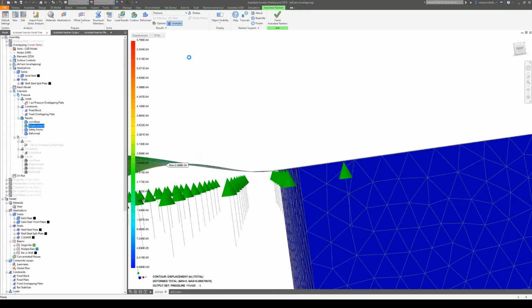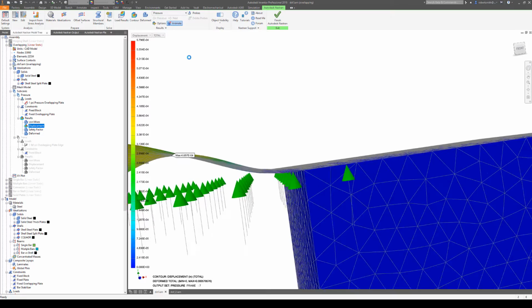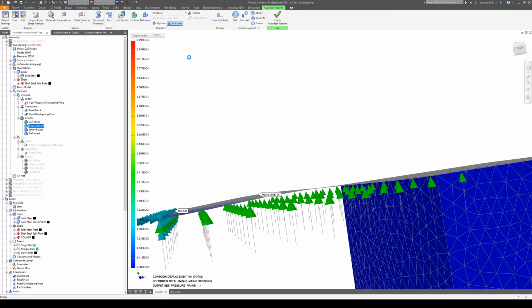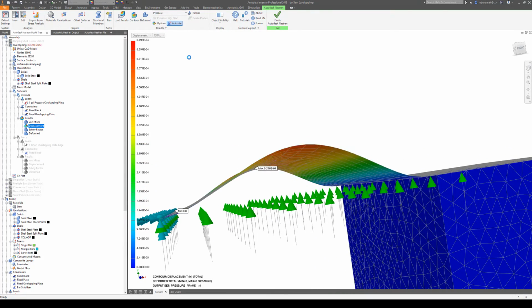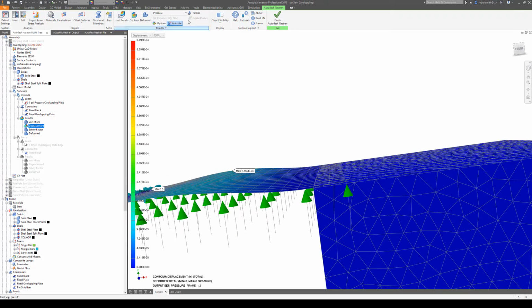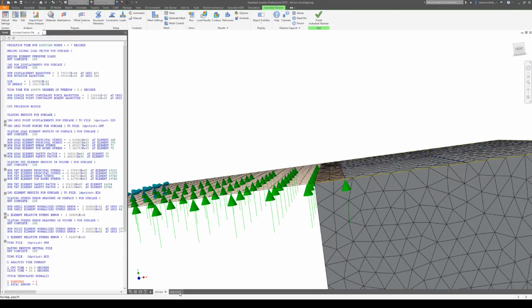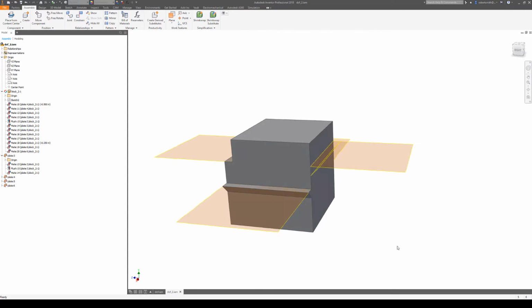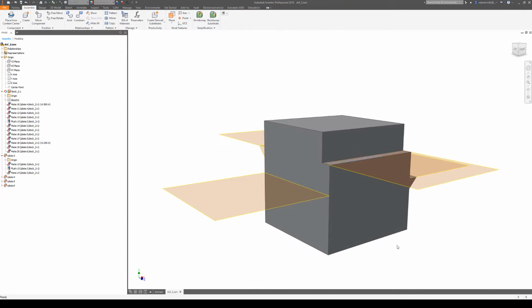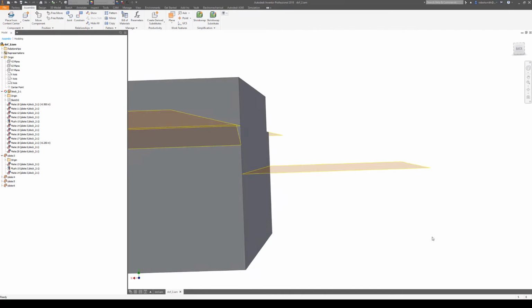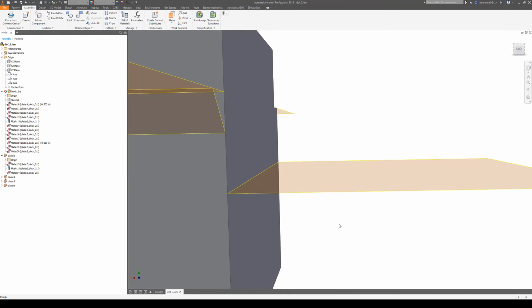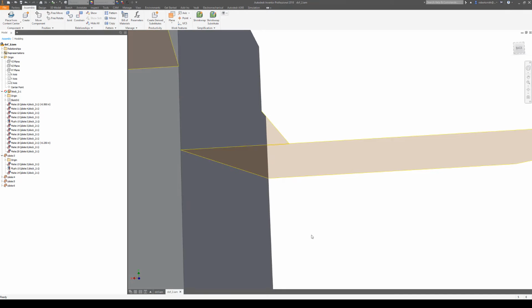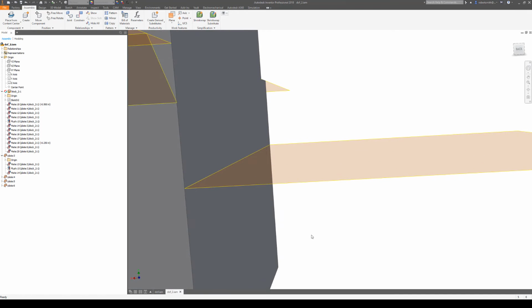And sure enough, I get the bending that I expected on both ends. In this other model here, I've just shown a few other ways that you can deal with that. Let's say this is a condition where a plate meshed with shell elements is going to be meeting up with the face of a solid structure meshed with solid elements. There's no way that I can overlap these two as modeled, like I did when it was at the top.